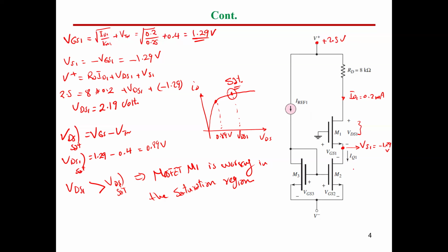Okay, guys. So for that, we call it now reference current circuit. Why reference current circuit? Because according to the current flowing here, you could have the same current moving in this branch. This is actually very important in electronics control. So we may need it in a lot of applications. Reference current or reference voltages are required a lot in industry. So this is one of the application circuits we use in MOSFET.